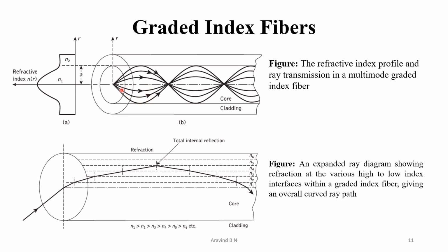That means when these several rays are propagating together, they get total internal reflection either within the core region due to the variation in the refractive indices, or based on the type of ray and other criteria, they may also get total internal reflection at the core cladding interface. That means the refractive index of the core is not linear, it keeps varying, but these different refractive indices within the core are always greater than that of the cladding value.